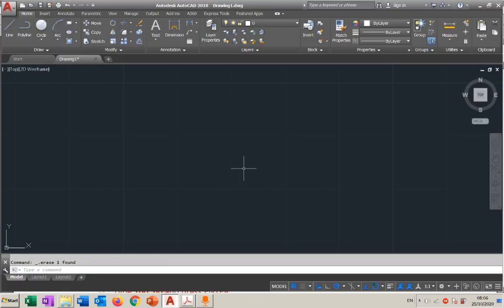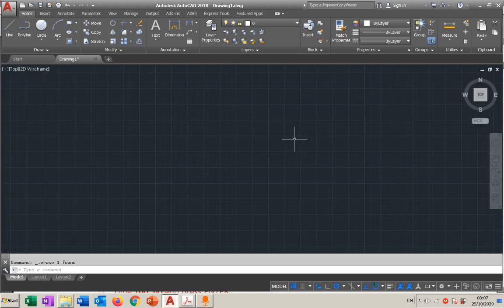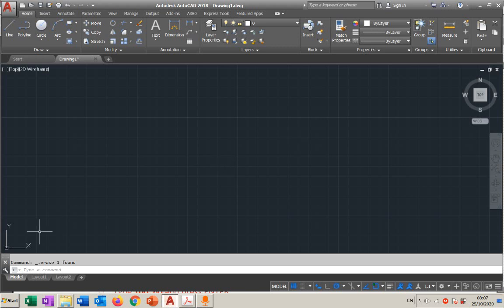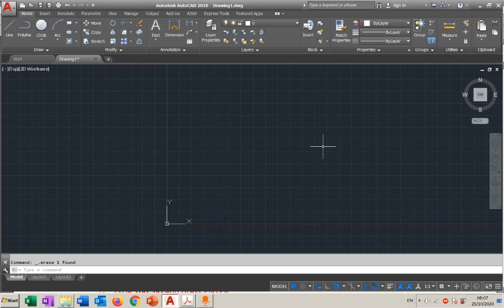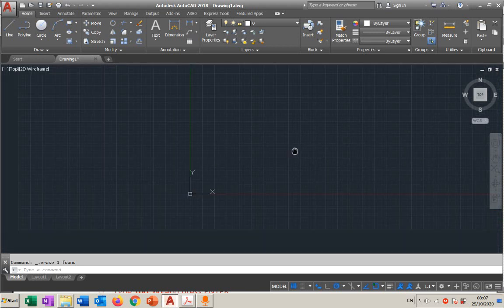First thing first is to set up the drawing area. We said that in this corner, when you say the x and y, this is the origin, yes? I will bring the origin to the center. So how to do it? First I'll zoom out until this comes out from the corner. Look, now I know where the origin is. So I'm going to press the wheel and hold it to adjust the screen.